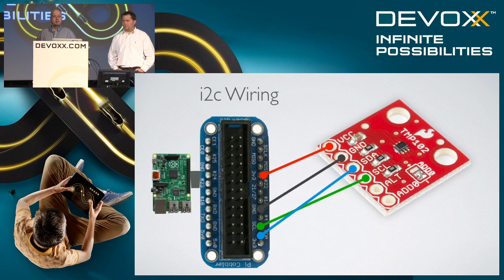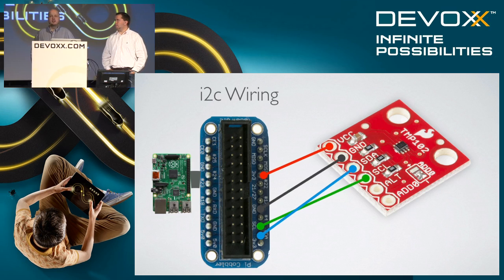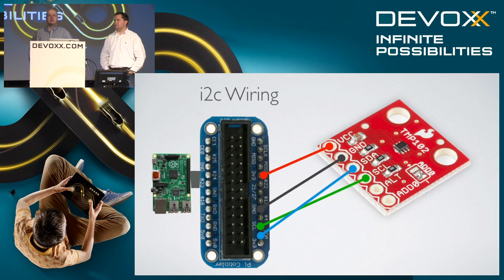So we then have our Raspberry Pi, and it's connected up with I2C to each of these little devices. I don't know how many of you saw the talk on Pi4J yesterday. We're going to be using the Pi4J library, and he talked about all the different ways you can connect up devices to a Pi. My favourite by far is I2C, because it's pretty much plug and play. It's much like USB for embedded.